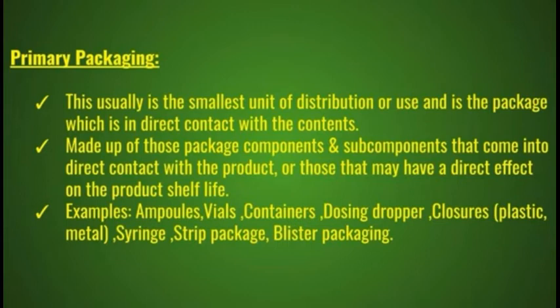Polypropylene has its heat sealing property provided by acrylic coatings or modifiers added to the resins. The fin seal wrappers are polyethylene and Surlyn. And next one is shrink wrappers.